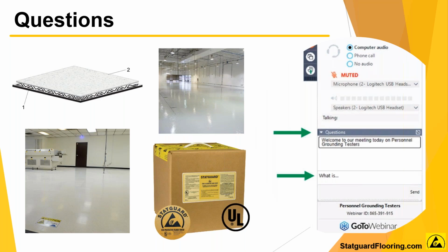We didn't discuss this directly, but for floor finish used over a non-ESD floor, can you talk a little bit about that? Yeah, our ESD floor finish will convert any non-ESD floor to dissipative flooring. What's required is an initial stripping to remove any finish from the manufacturer on the tile or any type of flooring being converted. After stripping, you follow up with a neutralizer to bring the floor to the proper pH balance of 7.0, which is neutral, and then apply the floor finish.